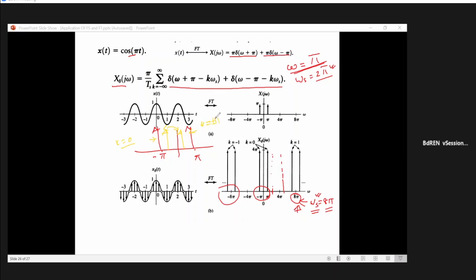So you see that for k equal to 1, not plus minus 1. K equal to 1. That means, for k equal to 1, your samples are coming within the bandwidth of your original signal. So this is actually appearing as an alias component if your sampling rate is not quite high, or does not satisfy the Nyquist sampling rate. This is in the frequency domain.